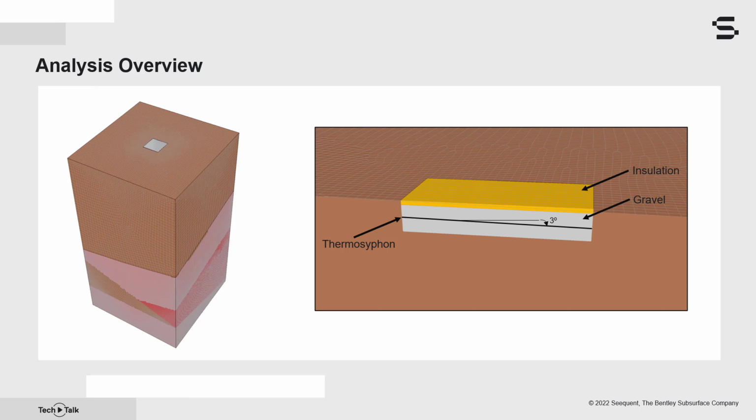They are 9.51 meters in length, 88.9 millimeters in diameter, and are 1 meter deep on average. Each thermosyphon evaporator is connected to a 6.5 square meter condenser. The condenser is not included in the model domain as the thermosyphon boundary condition accounts for the whole thermosyphon system when applied to just the point, line, or cylinder representing the evaporator.